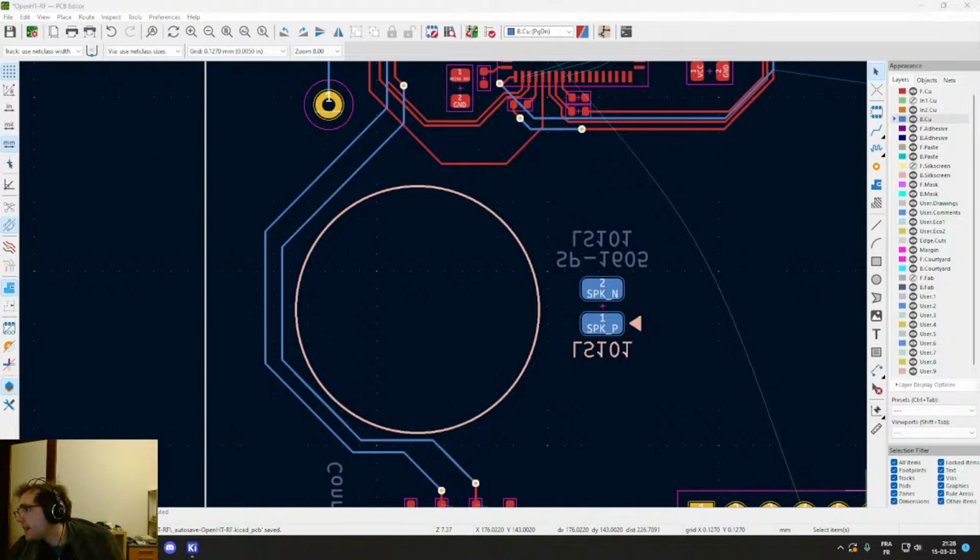Okay, so yeah, invalid.code. Yes, we could indeed swap the FPGA image when switching modes. This is completely feasible. It would have a few milliseconds of downtime, which is not much, and we have a few megabits of NOR flash memory on the Nucleo board that we can use to store all the FPGA images.